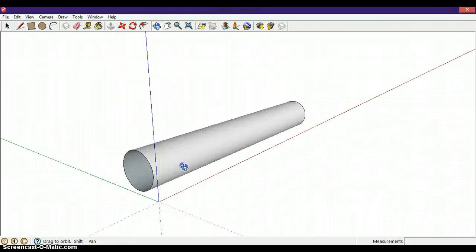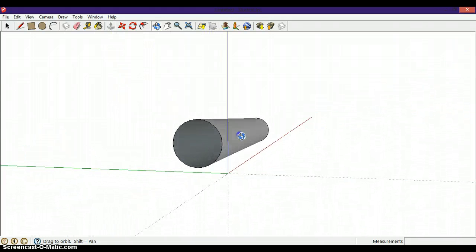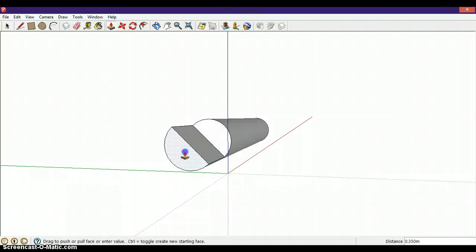Another thing which you can do in Google SketchUp is, obviously, you can draw lines. To do so, hit L on your keyboard, and you get a pencil, and just draw a line wherever you want it. So over here, I will make the diameter for the main circle. Now over here, I can also pull and push away any of the segments which I've now made. And I can just keep on doing so after I draw a line. When it says offset is limited like it just did, all that means is you have to pull again, because Google SketchUp got a tad bit confused.